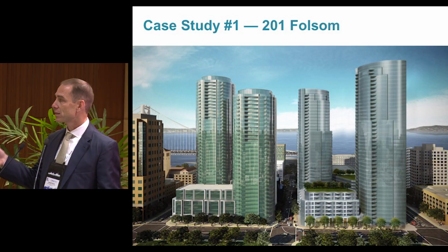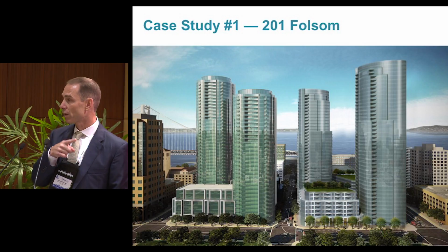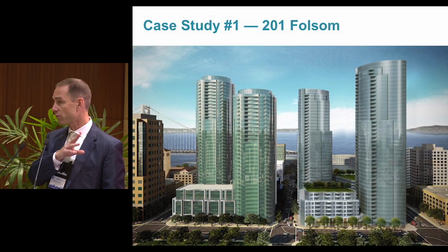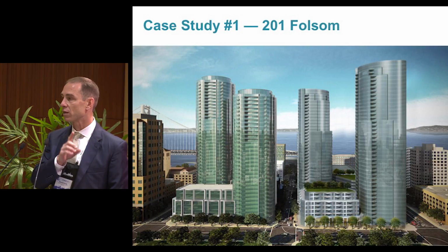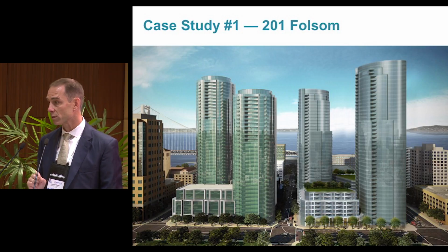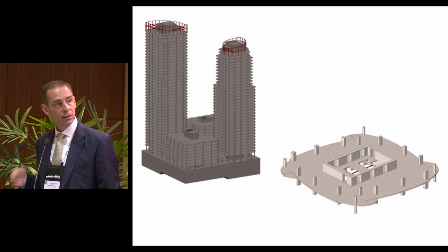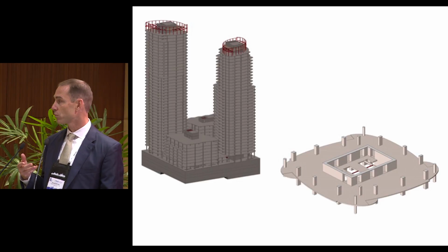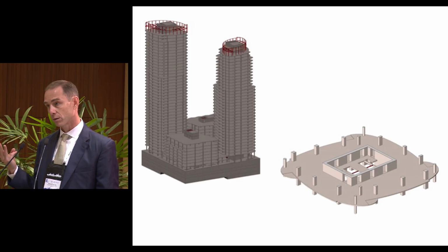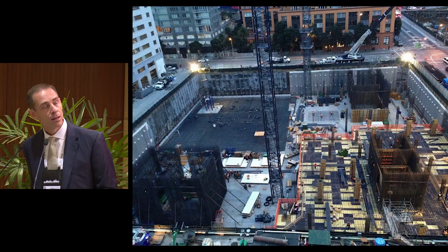Now, Tally didn't exist, and EPDs didn't exist when this project started, so this is an optimized design for value-based design. There's fly ash in the mixes, but it wasn't done for low-carbon specific purposes, but we did it as a look-back process. We pulled up the Revit model, and we've looked specifically at the structural frame, so I'm looking at the concrete, rebar, steel, formwork, post-tensioning to do this evaluation. So I'm really just looking at the structural components of the building.